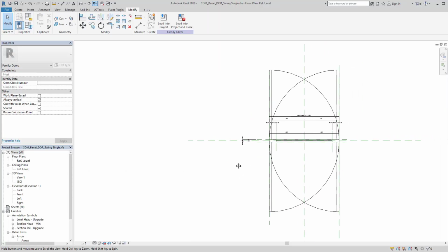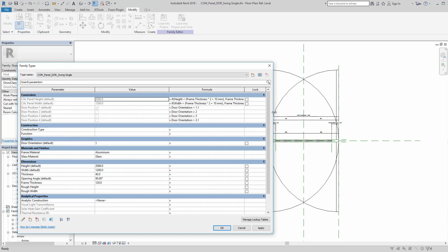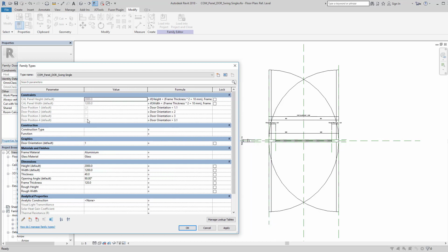So if you need to control multiple states, more than two, where the toggle is not going to work for you, you ultimately need to switch between, in this case, 4 states, and it's important that you don't have all of them turned on at once. Rather than having 4 separate tick boxes that the user has to make sure they've only got one ticked, you can create an integer parameter here.